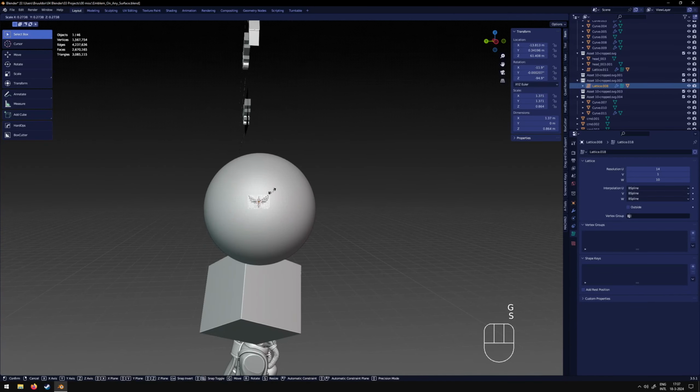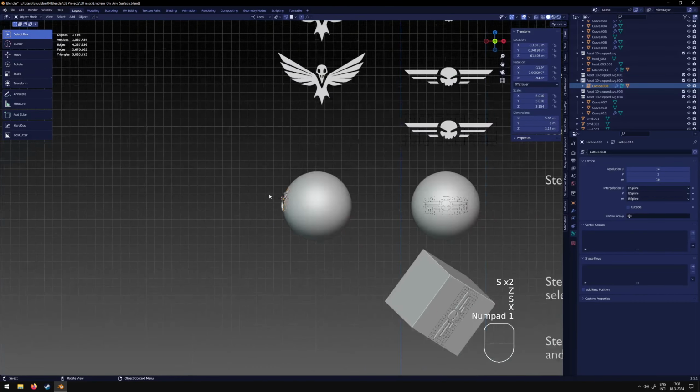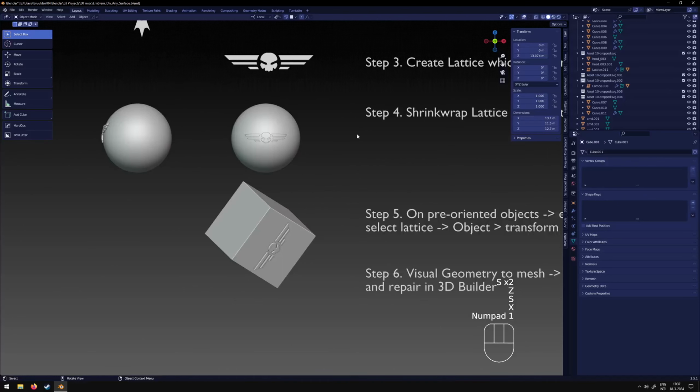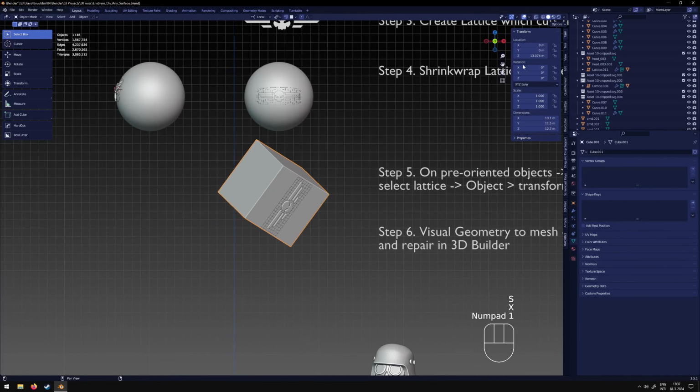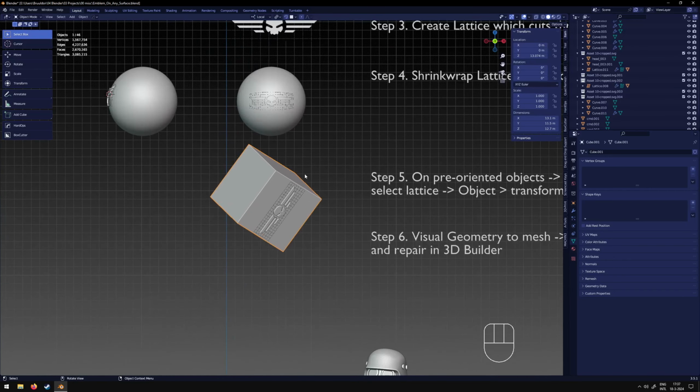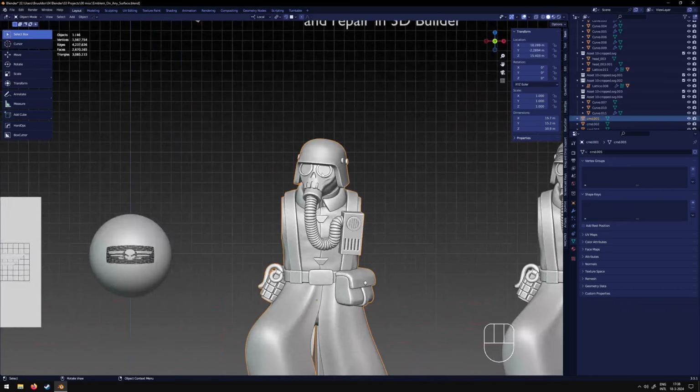We can scale it, we can make it smaller, we can scale it lengthwise, widthwise, we can do all sorts of stuff. And as you can see, we can do this on any object, even on objects upon which we don't know the orientation from, the rotation from. This is usually how an STL file will be imported with 0, 0, 0 rotation in the transform box, such as this STL file.